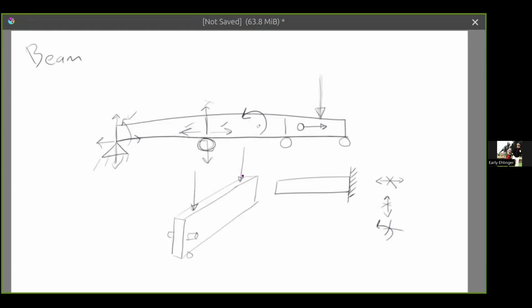And what differentiates a beam from some other type of structure is that the twisting you're applying has to be in the same plane as the beam. Same thing with forces, right? So we can have something pulling on the beam through the length of the beam. But what we can't do is have something pressing against the side of the beam. The most we can do in that orientation would be to have something grabbing the beam and trying to bend it like that.